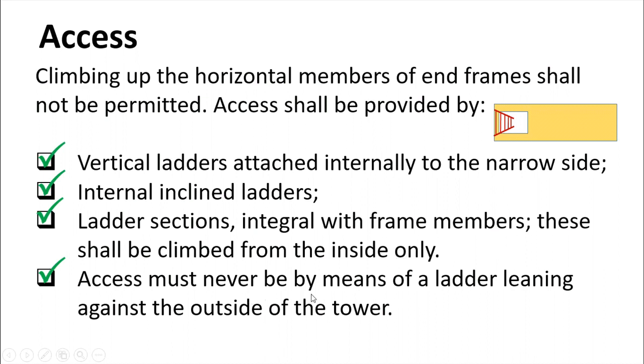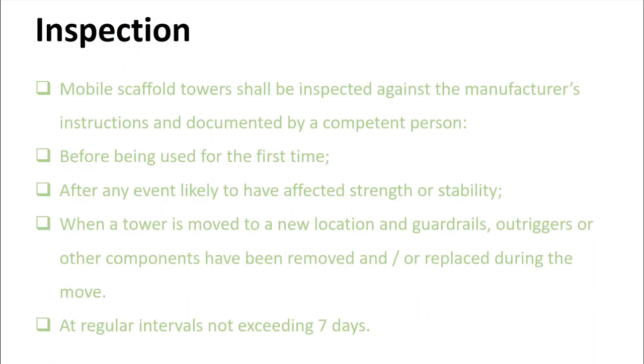So this will make the scaffold unstable due to the imposed live load when you are climbing on the ladder. So it may trigger accidental movement of the tower due to your weight.